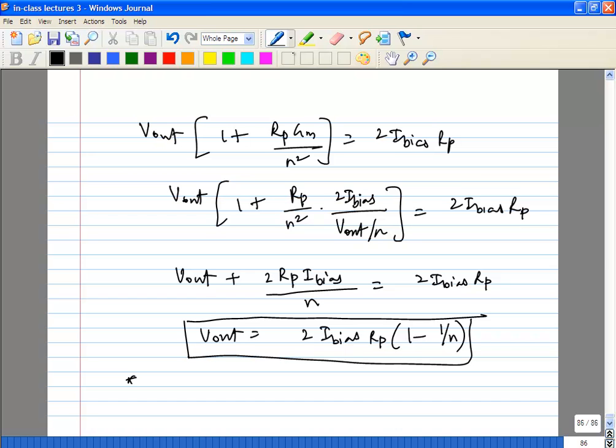Okay. Of course, the last thing to remember, for startup, so let's say the oscillator is starting up, you should remember that you use the small signal g_m, not the large signal g_m. Okay, just make sure for your small signal loop gain.